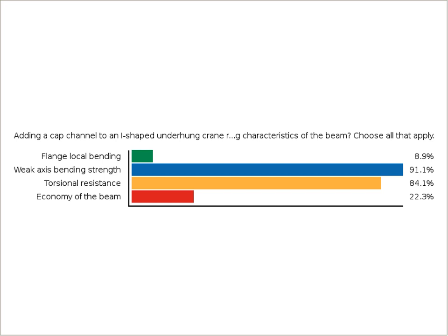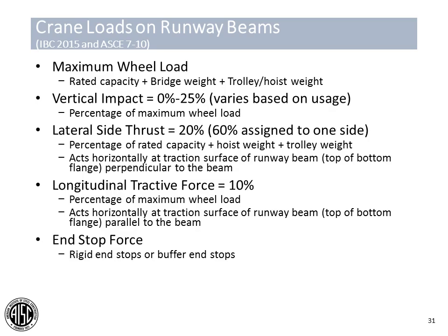Okay, thank you, Luke. Let's move on to question and answer. I'm going to take us to slide 31. We had a couple of questions on this slide, specifically the longitudinal tractive force of 10%. Can you reiterate, is that a percentage of the maximum wheel load of just one wheel, or of all the wheels? So technically it would be of all the wheels.